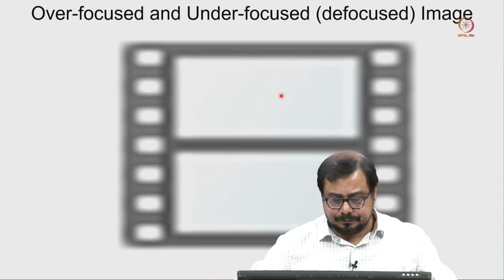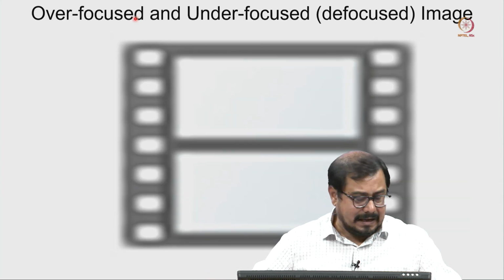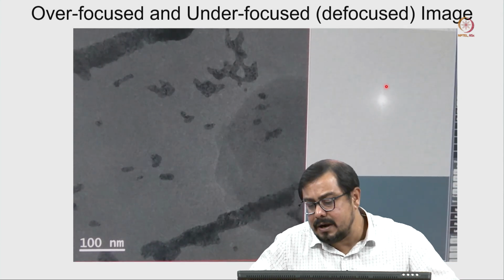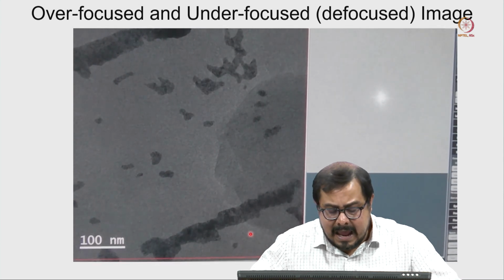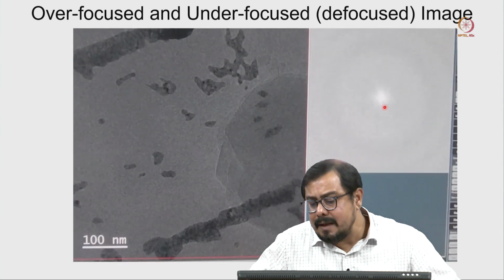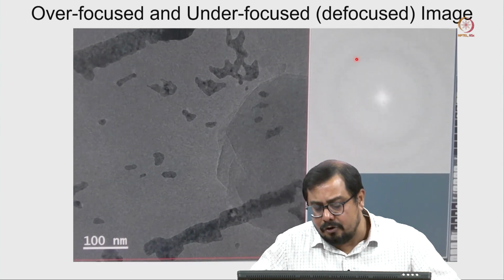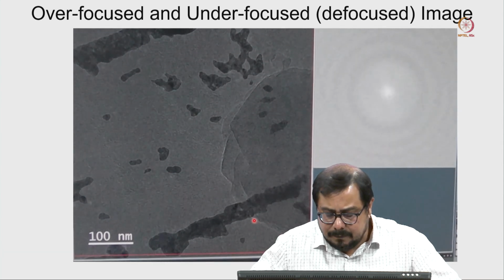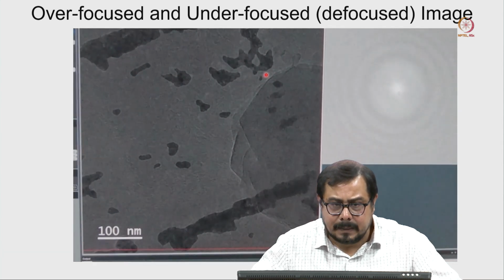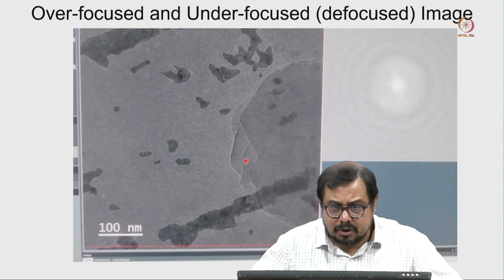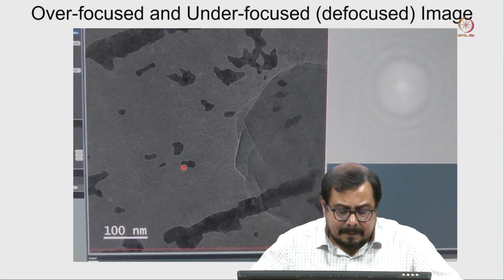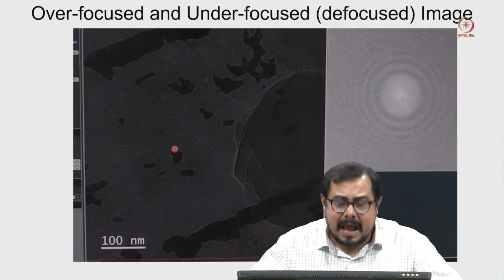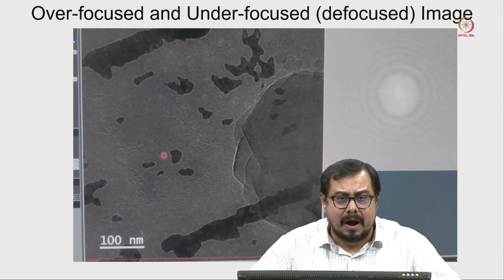Let us take a look. So, here there is an image. In this particular case, pay attention to this one, and this is the power spectrum. This is basically the actual sample. Now, I am gradually increasing the defocus, and if you look at this boundary, you can see a white fringe outside this particle, and that is helping us to see the particle clearly. Even for those small objects, you can see there is a boundary outside, and in most cases this boundary is a white boundary.